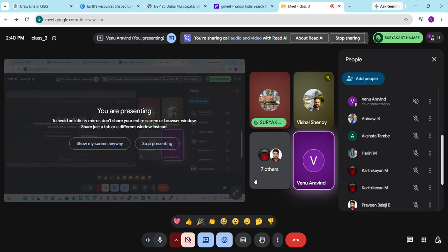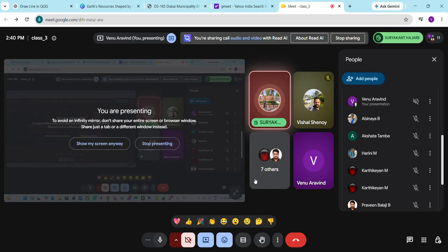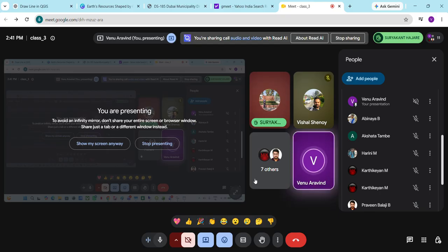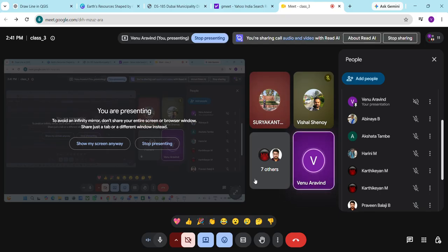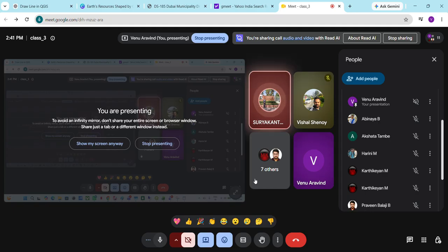Yes, Surya. In Sag means 100% of the water will be collected in that particular gully. On grade means only some amount of water, whatever we mention in the design constraint. 100% means it will take 100%, but we can mention 60, 50 like that. So with on grade, some amount of water will be transferred to another gully. Yes. Okay.